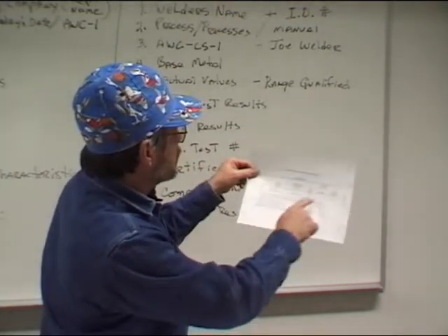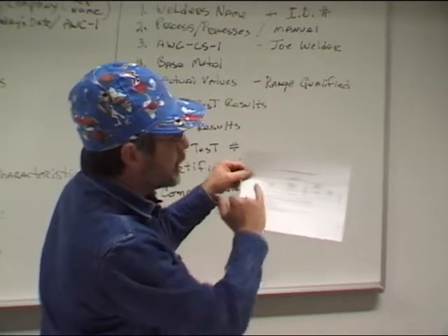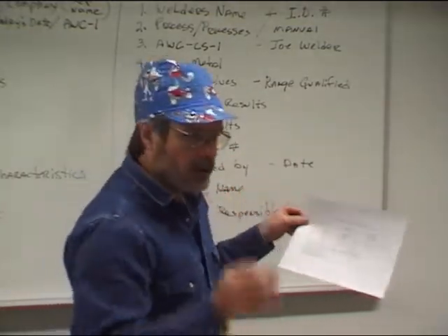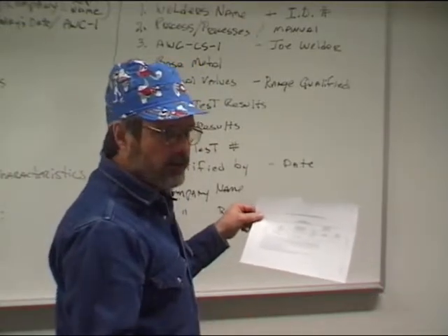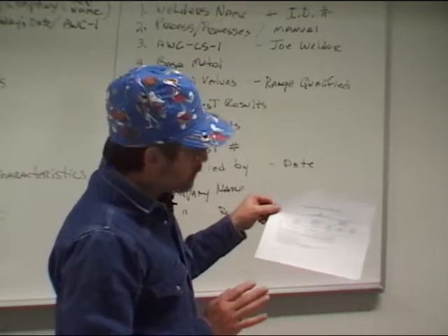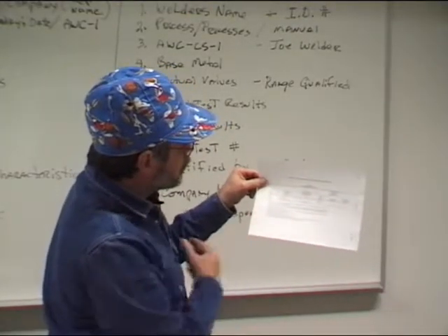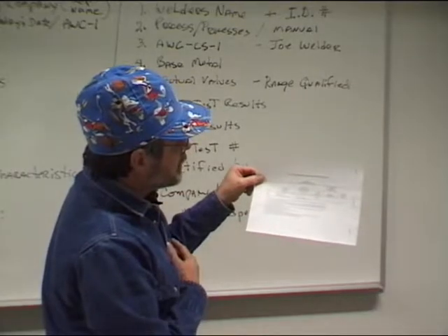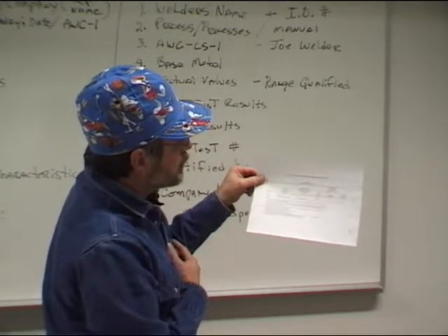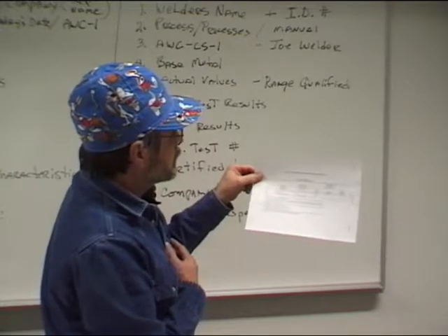But you have to look at the notes. And so here it says thickness of coupon, and you read note 1. And I want to say this again. I've said it before. Always remember that the big print giveth and the little print taketh away. So it'll usually set limitations on what can be done. So under thickness of coupons, read note 1. It says, when using 1, 2, or more welders, the thickness T of the deposited weld metal for each welder with each process shall be determined and used individually in the thickness column.